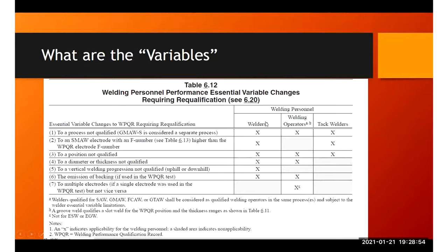Here's a statement that's different than, maybe, for those of you with experience with ASME. In D1.1, if a person does a manual or semi-automatic process test, they're also qualified as operators. ASME Section IX doesn't allow that. It's different. But reading through those footnotes will help you out and keep you out of trouble, in case some pain in the rear end CWI who likes to study welder qualification comes and looks at your paperwork, because that happens sometimes.